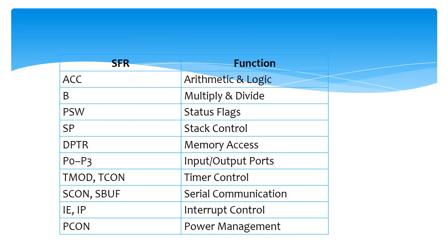And this is a summary that is given. You have the registers called SFR on the left side, and the functions given on the right hand side. All these SFRs will have an inbuilt address. So one can use this kind of English-like word, or otherwise one can use the address in the instruction so that the processor can understand. So these are some of the special function registers and the CPU registers which are available in 8051.